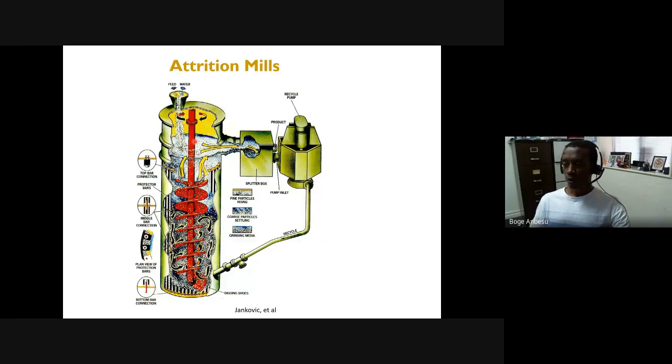And we also have a screw agitator, which means you're going to produce a lot of attrition inside the mill itself, because this screw agitator moves the particles, the small ball media, and so on. And that's going to give you very high contact between the ball and the particles. And you tend to produce fine particles, or we actually call them ultra fine particles. So if particles are below 20 micron, usually we call them ultra fine particles. Okay, it's just a terminology.